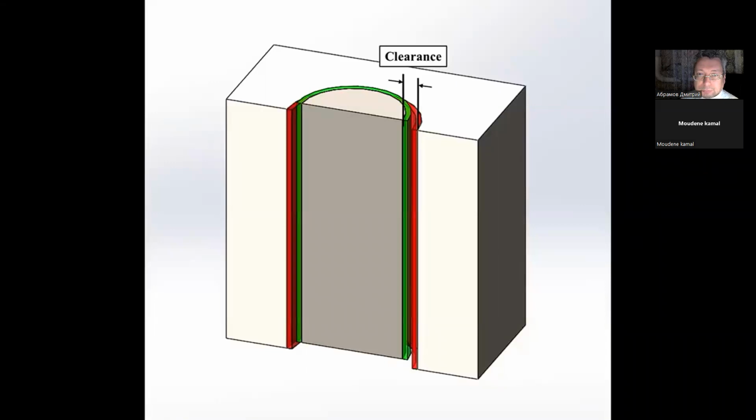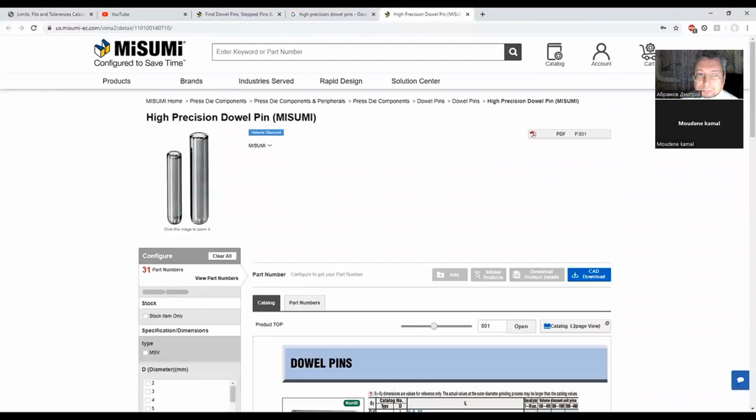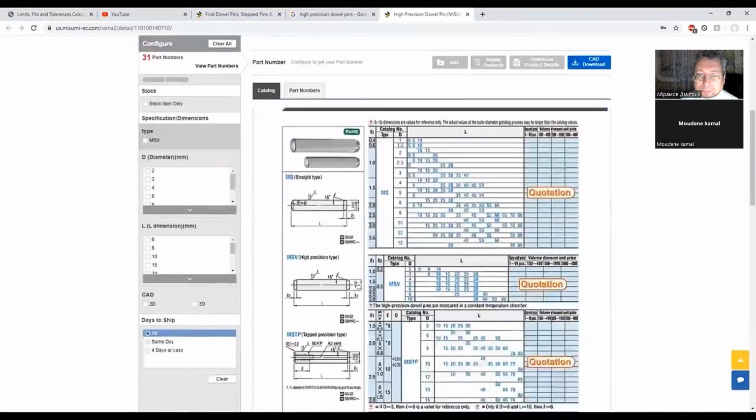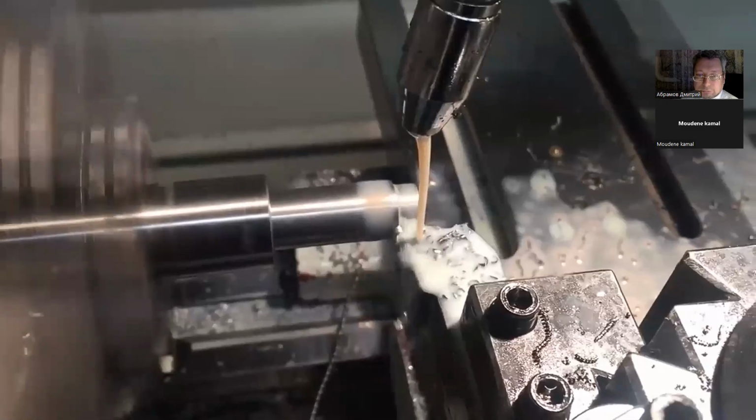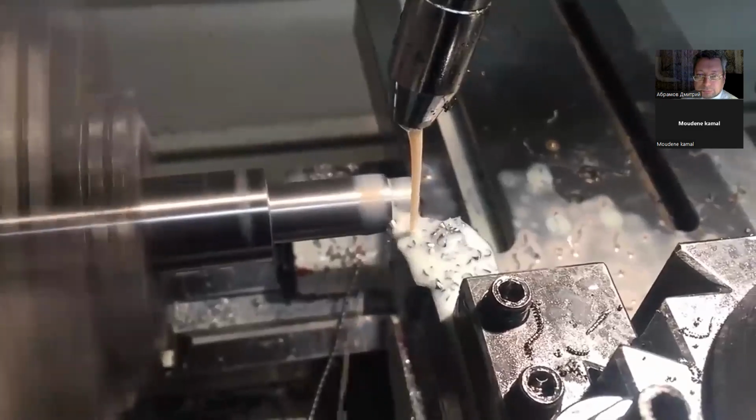If the clearance is too large, the fit might not work. The only way to change the clearance without changing the allowance is to tighten up your tolerance zones, either by changing your manufacturing methods or buying tighter tolerance pins. Conveying tolerance zones can be a bit annoying. Say you own a factory that makes dowel pins.